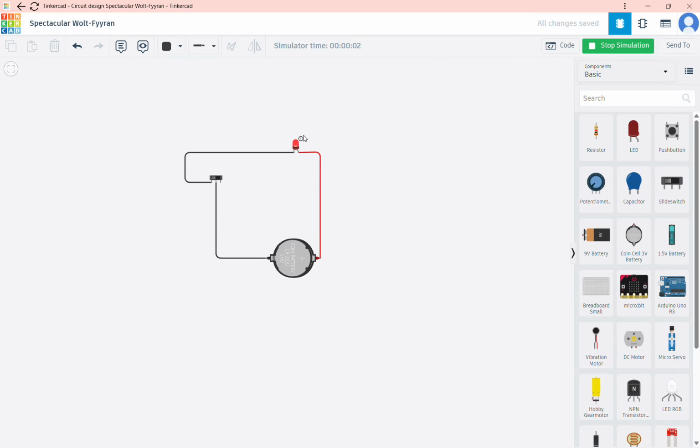Now it's turned on, but you see this is giving us a warning. Current through the LED is 61.9 milliamperes, while the recommended maximum is 20 milliamperes. The usable lifetime of the LED may be reduced. It means that we can't use this LED for long if we apply a current of approximately 62 milliamperes to it. So to do that, we usually add a resistor. Now if you press the switch, terminal 2 will be on, making sure that this LED goes off. It opens terminal 1 but closes terminal 2.